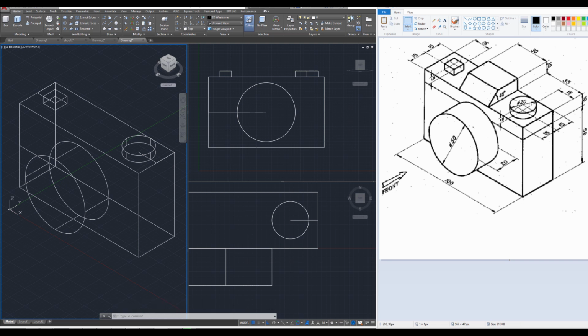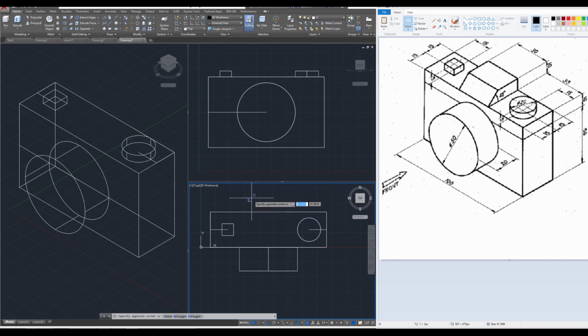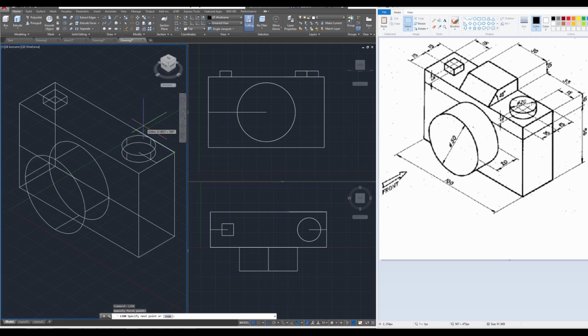Lastly, we need to draw out this little lens portion, or the flash portion, I guess, and that is kind of the best way to draw. It's from the right over here, the right side, and you can tell it's right because of this. So before we switch on this top view over here, let's just draw out where we're going to have it starting, and that's going to be 35 units across. So use the line tool, enter, then click on the isometric, click on this corner, and move out 35 units. So I'm going to type in 35 and press enter right there.